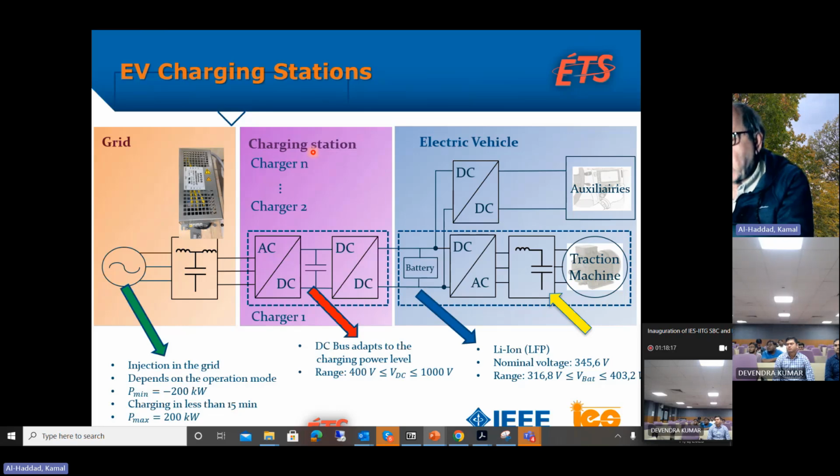So everybody wants to charge, and every electric car battery's kilowatt hours is going up. We used to have 20. The first Nissan car was 16 kilowatt hours. Now the least Nissan car has a 40 kilowatt hour energy storage battery. So if your battery charger is 10 kilowatts, you need minimum 4 hours to charge the car, and so on. So we keep on increasing.